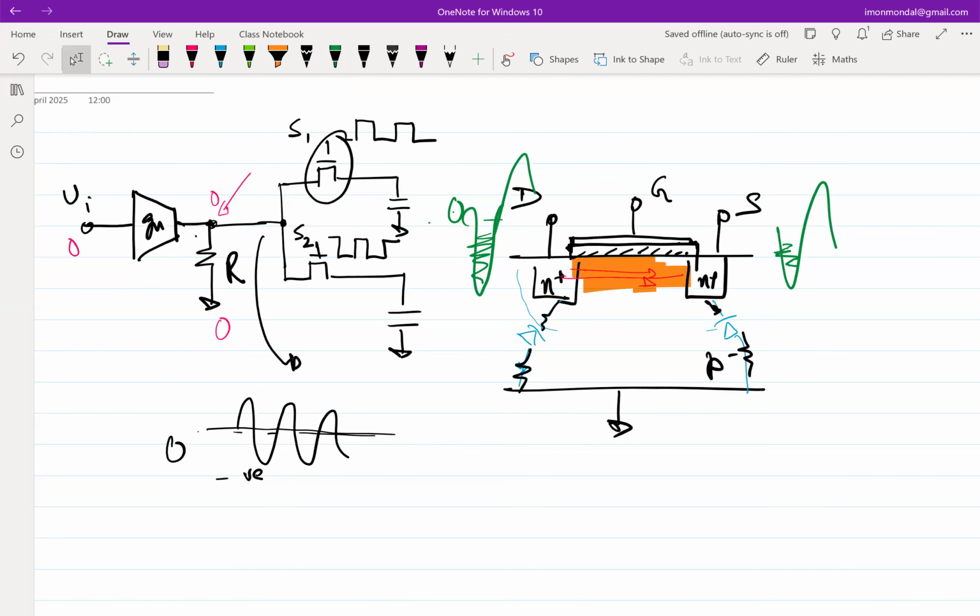It's not a very highly doped P. It's not a metal. You are going to have resistances, which means that when current flows, you are going to have significant amounts of positive and negative voltages across these PN junctions, and not only across these PN junctions, but across the substrate. This substrate, which is assumed to be hard ground, can have negative voltages at different places of the substrate.